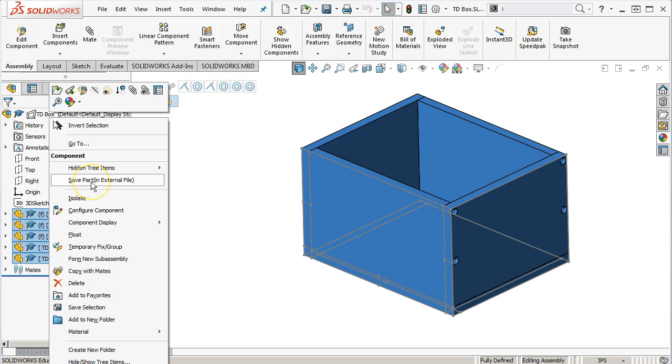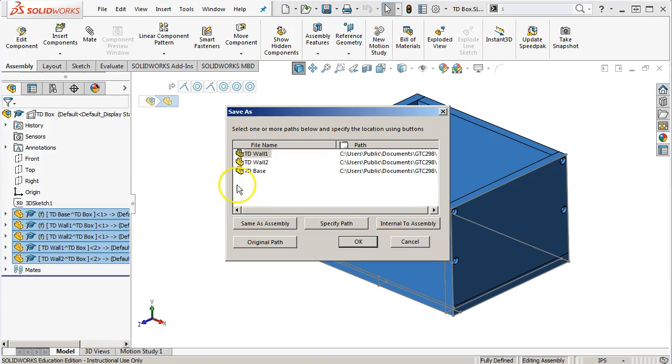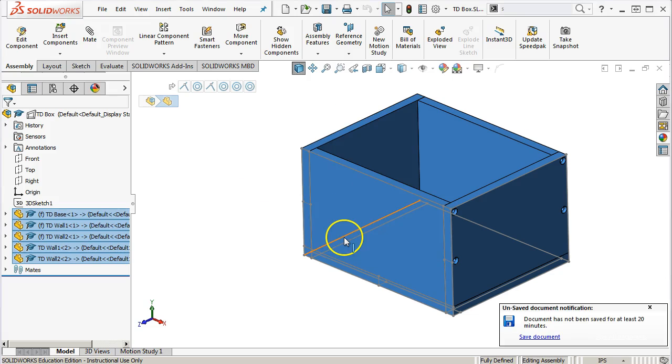We need to externalize, right? Because the virtual component is going to be difficult to get into a drawing. I'm going to want to possibly make configurations, put different geometries in the sides, be able to manage this in single units. So when I save the part in external, we're going to make sure it's in the same as the assembly, hit OK.